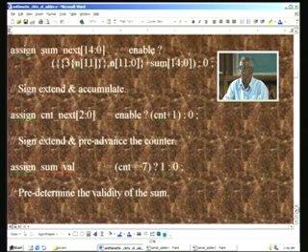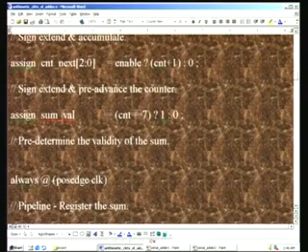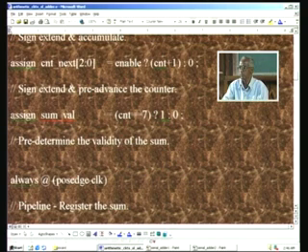And the next statement is the sum valid, which is also a signal that is ahead of the actual sum valid, which will be registered later on. This is assigned using an assign statement, and only when the counter is 7, that is to say all the 8 inputs are already fed, and when n7 is arriving, at that point of time we make the sum valid, because with the subsequent clock the entire computation is over, that is after 8 clock cycles.